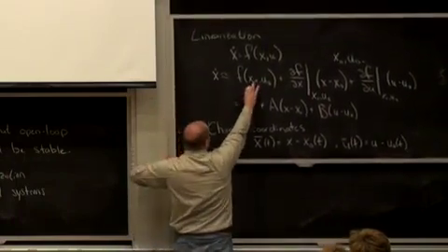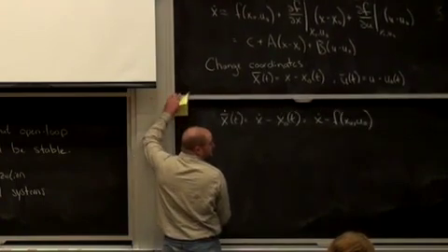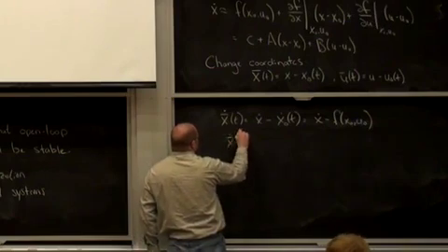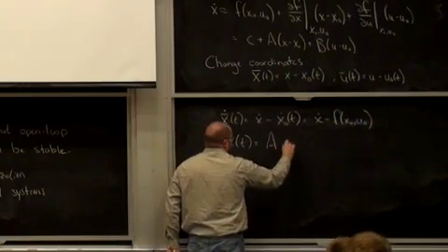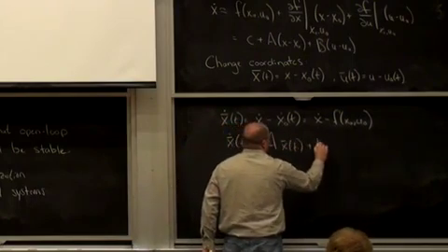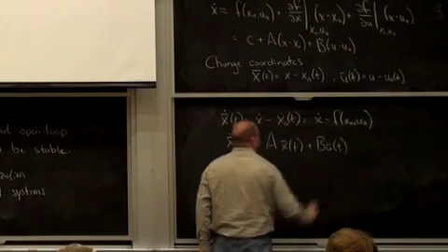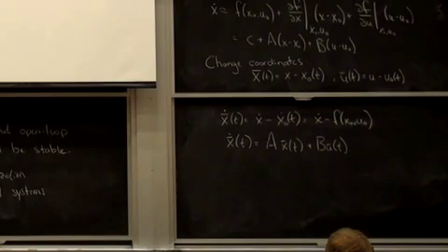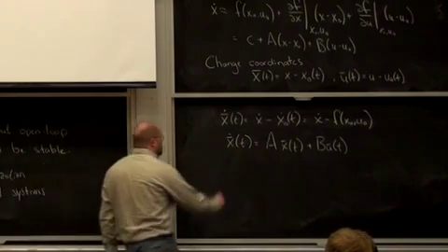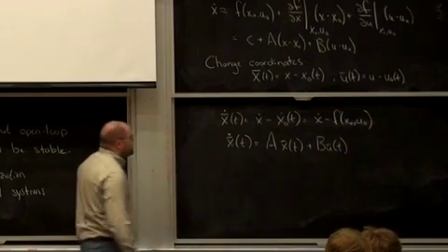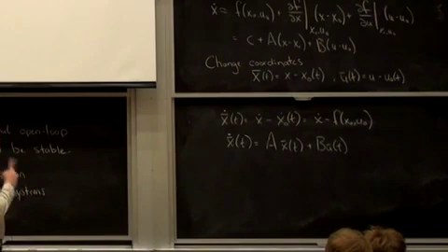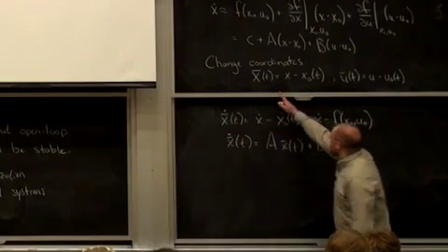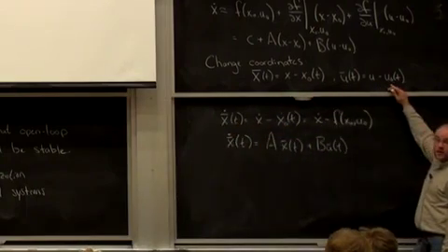This term here is taken care of in this new coordinate system, which allows me to write the whole thing as x bar dot equals A of x bar. You with me on that? Linearizing a system at a more arbitrary point, well, doing a Taylor expansion results in a linear system only if you change coordinates to lie on some system trajectory, okay?